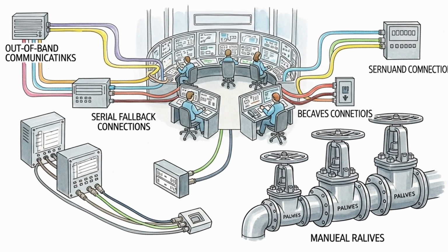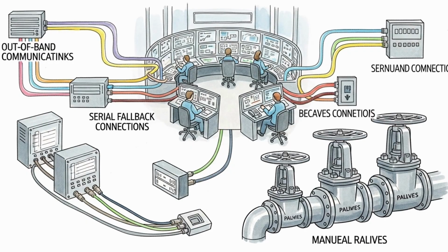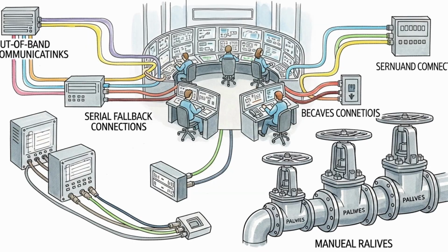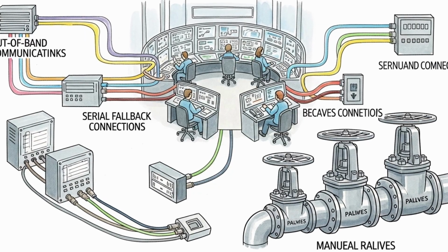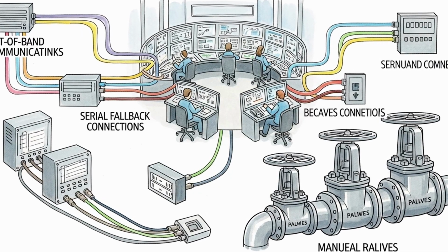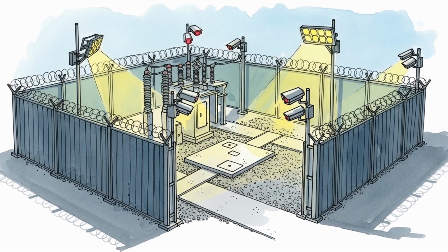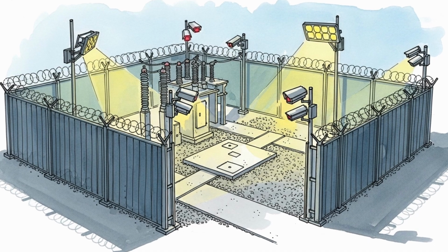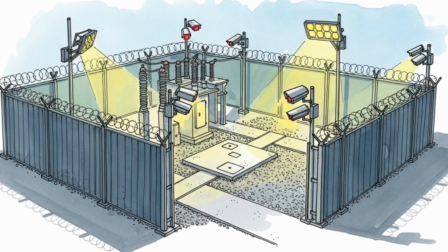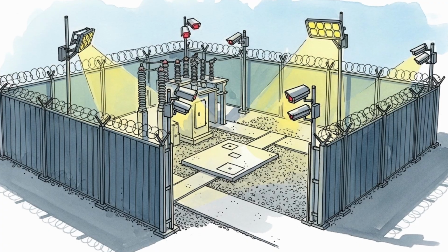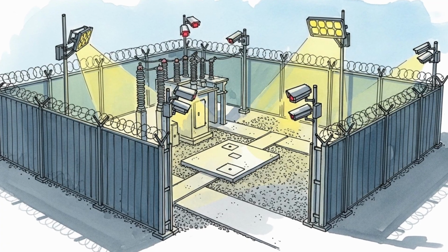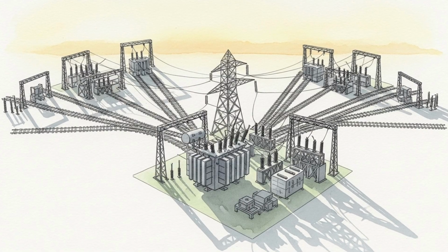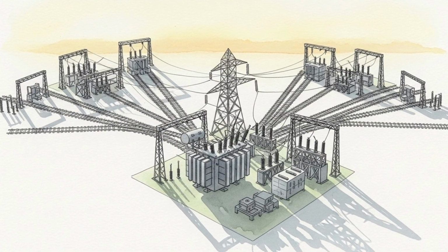Catalog maintenance becomes more difficult when drag rises. Radar and optical sensors must track more objects that are changing altitude and period quickly. Two-line elements lose accuracy faster. Screening volumes for close approaches become larger. False alerts increase. Coordination between operators, tracking networks, and traffic management services becomes critical. Short planning cycles replace weekly cycles. Maneuvers are timed to avoid peak uncertainty and to maintain safe separation from neighbors in the same shell.